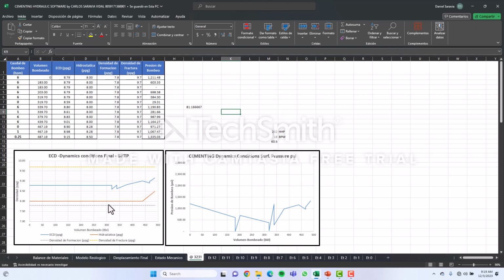And always here is the reservoir pressure. In these calculations, we calculate density in ppg, pounds per gallon, and here is the frac density. You can calculate frac pressure; frac density is normal. So this is the operating window: our pumping circulation bottom hole treating pressure must be over the reservoir pressure and below the frac gradient.